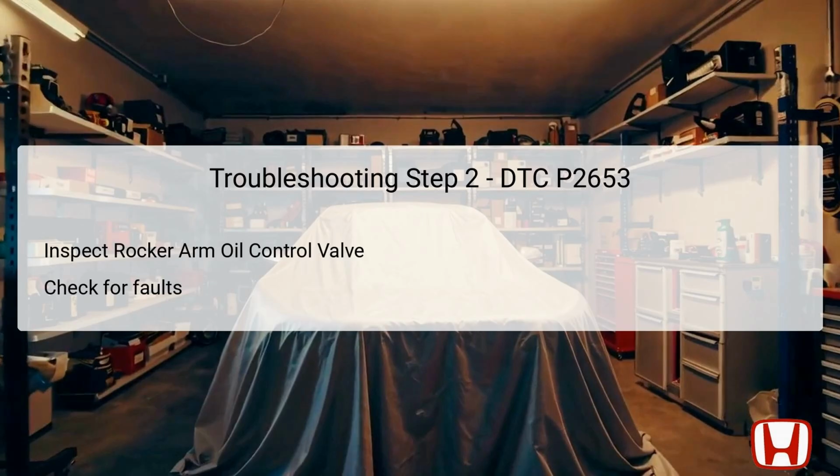If the measurement falls outside this range, it indicates a fault with the rocker arm oil control solenoid itself, possibly requiring replacement. Identifying and resolving any faults in this component is critical, as a properly functioning valve ensures the effective regulation of oil pressure to the rocker arms.